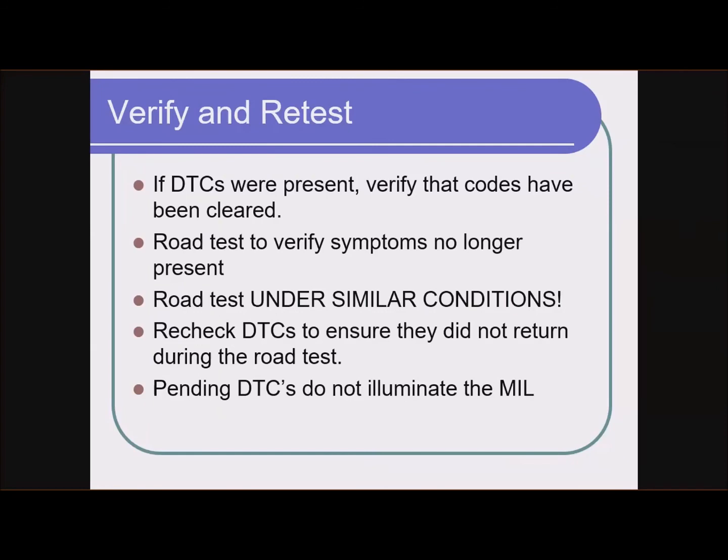Reason being, getting that evap monitor to run probably involves an overnight cold soak and then some driving. So it may not be practical for something like that to absolutely verify the repair before returning the vehicle to the customer. In that case, it should be explained to the customer that the monitor won't run until the vehicle sits, and I'm sure they don't want to leave the car for a week so you can make sure all the monitors have run.